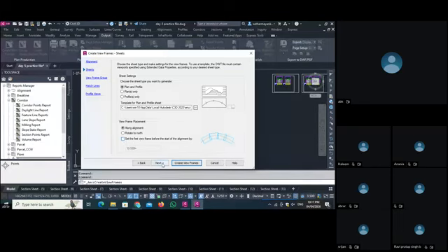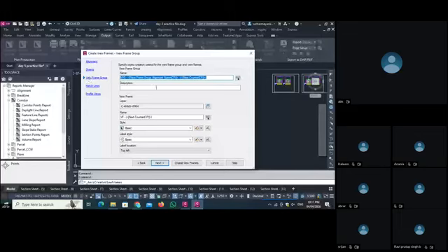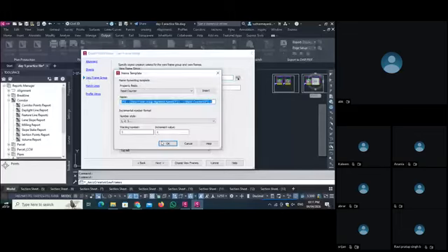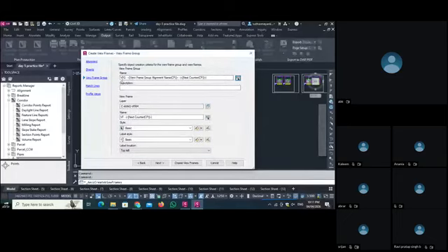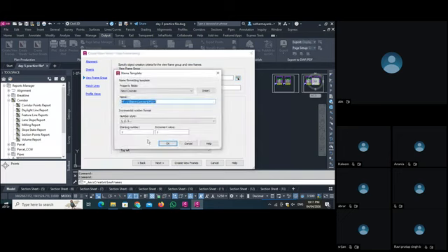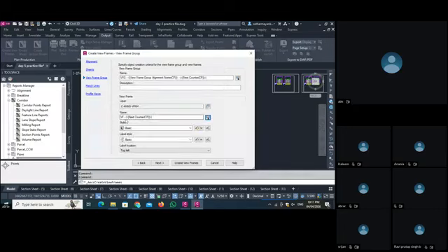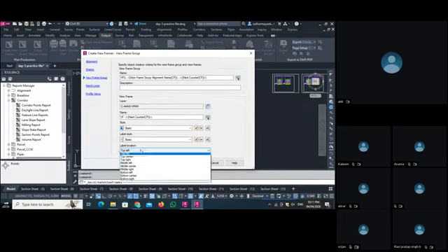Then I go next to the view frame group. If you want to give a name, you can select the name. The starting number is 1, so this takes VFG1. If you want to provide a description, you can set it here. The layer and the sheet name are also here. I just check that the starting number is 1. Then the style you can set from here, or you can edit this. The label location, you can set at any position.